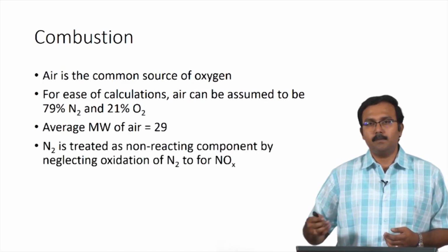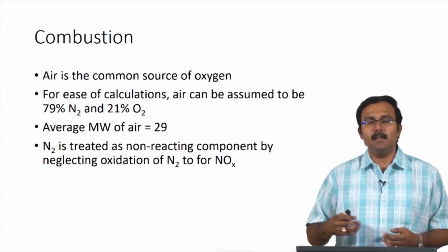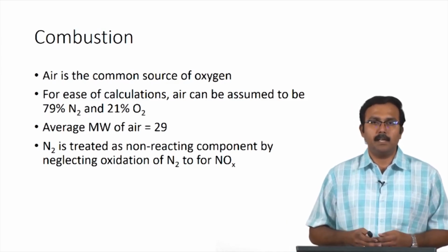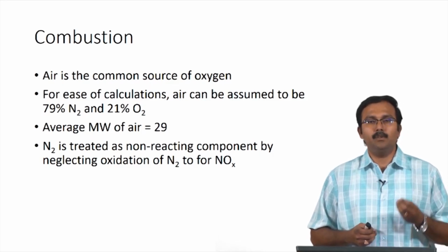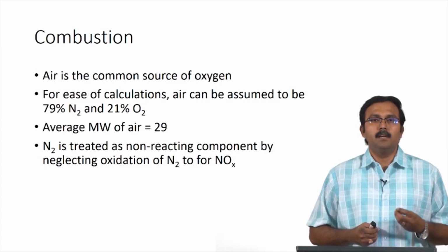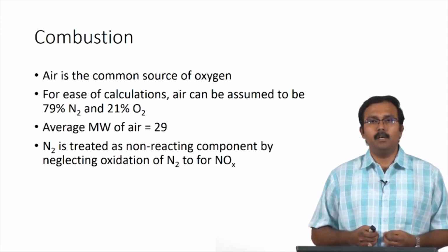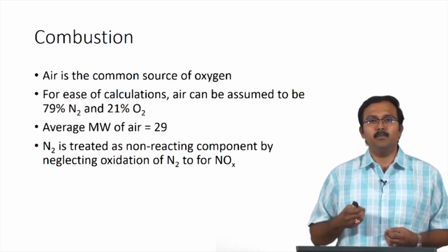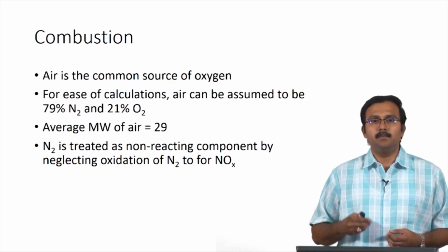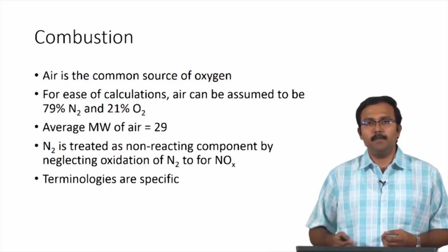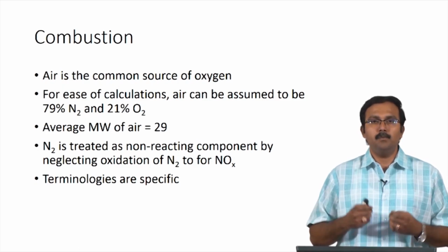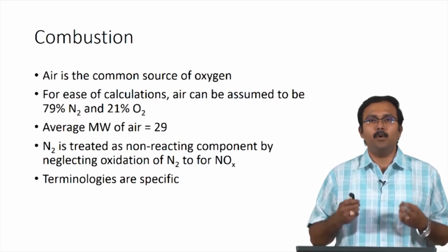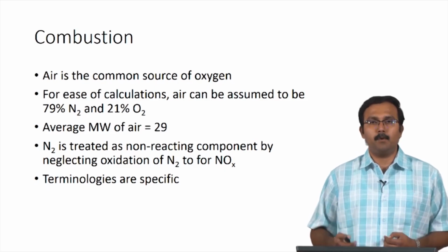So, nitrogen which is present in this air is treated to be an inert component during the combustion reactions. In reality, some amount of this nitrogen can actually get converted to NOx gases which are pollutants. These are usually in very small quantities. Because of this, they are considered to be negligible and are usually ignored while we perform these calculations. So, this particular process has specific terminologies which are associated with combustion processes. For this reason, it is important for us to learn and remember what these terminologies are and apply them appropriately.